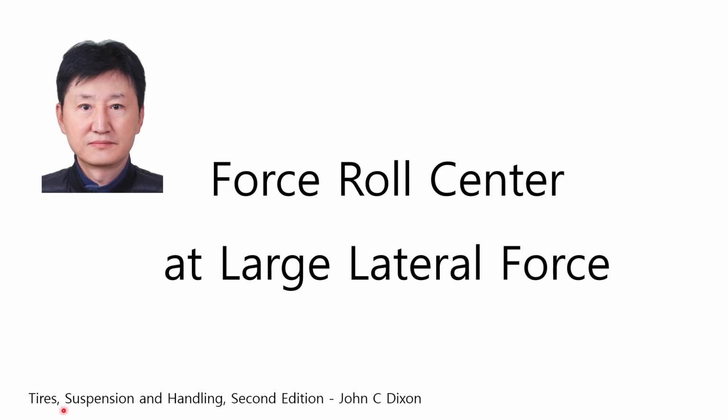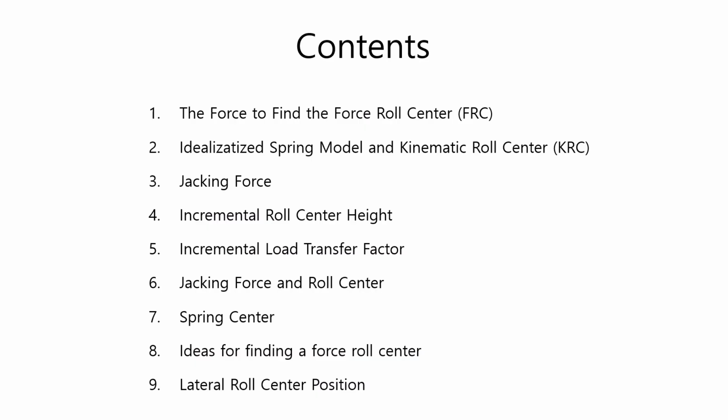The main idea of this video is featured in John Dixon's book, Tires, Suspension and Handling, 2nd edition. Let me introduce the contents of this video. First, we will look at the force to find the force roll center, FRC. Then we will look at the idealized spring model and kinematic roll center KRC, jacking force, incremental roll center height, incremental load transfer factor, jacking force and roll center, spring center, ideas for finding force roll center, and finally the lateral roll center location.